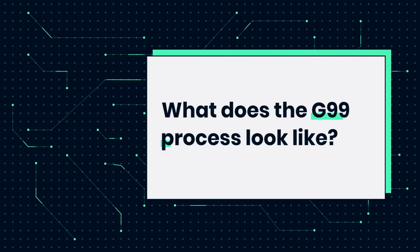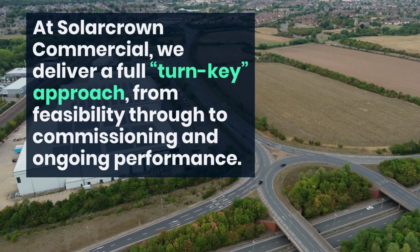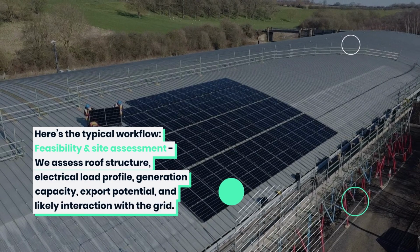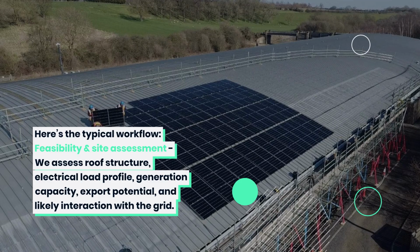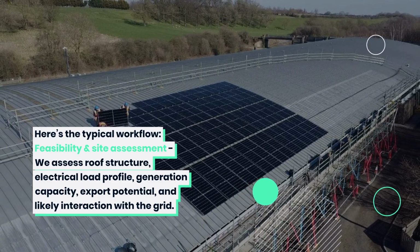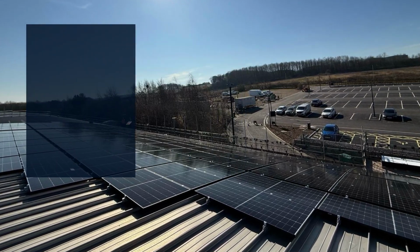What does the G99 process look like? At Solarcrown Commercial, we deliver a full turnkey approach from feasibility through to commissioning and ongoing performance. Here's the typical workflow. Feasibility and site assessment. We assess roof structure, electrical load profile, generation capacity, export potential, and likely interaction with the grid. We determine whether a G99 application is required. For most commercial installs, it is.